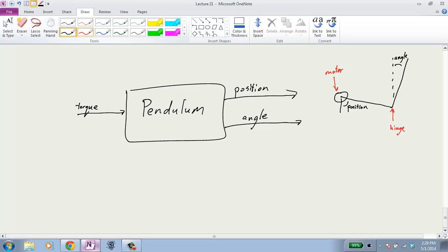So the first thing we're going to do is try to make some positive feedback so that when it's on, as you spin it, it'll try to cancel all the friction and spin as if it's frictionless. If I tap it right now as it's off, it stops right away. But it can use the sensor that senses how fast it's moving to add in additional torque to cancel the friction.